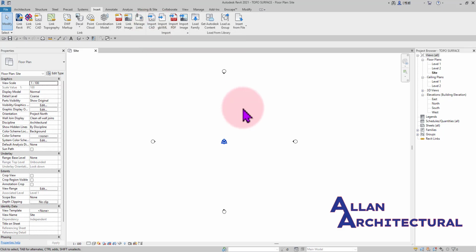I do not have the opportunity to change something and have it change in AutoCAD. That is the difference. If I import, it means it's exactly what it is. So I'm going to import that AutoCAD file, but you guys can try and link the CAD file if you want.